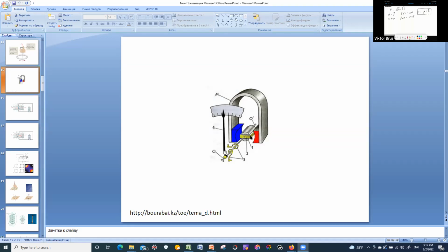So the larger the current that flows in the electric circuit, and thus inside this current loop of the ampere meter, directly proportionally to this magnitude of electric current, the torque exerted on this current loop from the side of this external magnetic field will also increase.